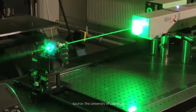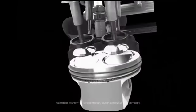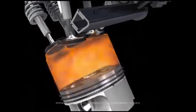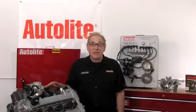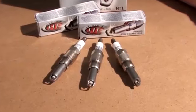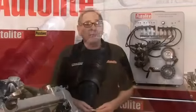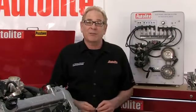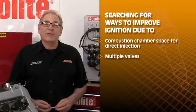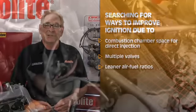Laser ignition systems are being developed right now by many automakers. As you saw in Module 1, with many engines transitioning to direct fuel injection, real estate in the combustion chamber is becoming scarce. The current crop of spark plugs is just too big, and that takes up too much of that valuable space. This is what's driving the development of plugs like the Autolite Revolution HT series, as well as 12mm and even 10mm conventional spark plugs. The need for combustion chamber space for direct injection, multiple valves, and leaner air-fuel ratios are prompting automakers to look for ways to improve ignition.